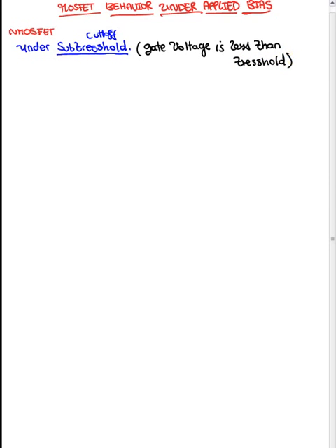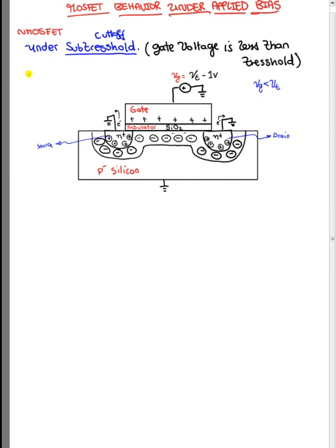Here is where you can apply it. Okay, so here's the visual model. The first thing to note is that the MOS transistor is operating in weak inversion. Remember what it means? It means that the fixed negative charges right here are a lot more than the electrons, just these two right here, right? Also note that the source and the drains are grounded, which means that the extra electrons here from these N plus materials are flowing directly to ground right here, right?